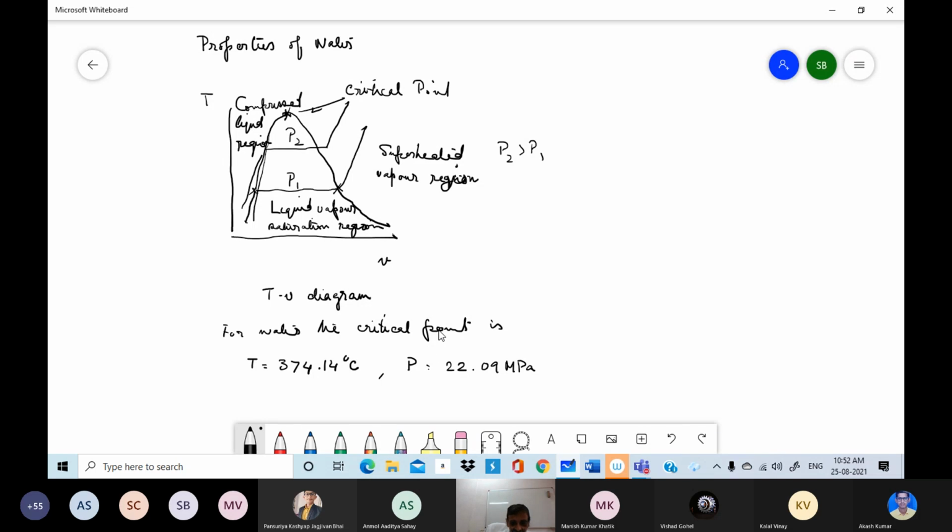Okay. So the critical pressure is around 220 times the atmospheric pressure. So that is why in everyday life, we do not observe that phenomenon of a gradual change from liquid to vapor without a boiling phase. But if you design your power plant to operate in that regime, then you have to take into account that this separation of liquid to vapor does not occur. So the design for the power plant becomes different.